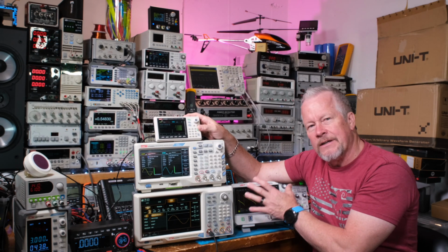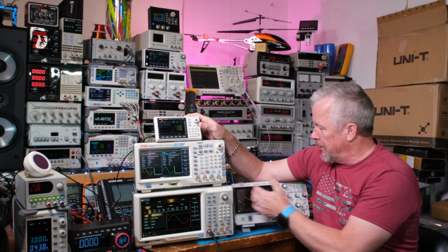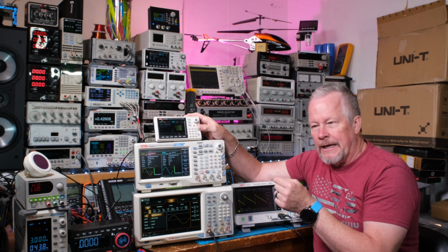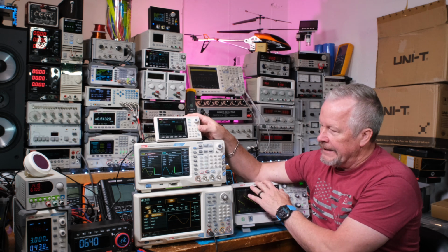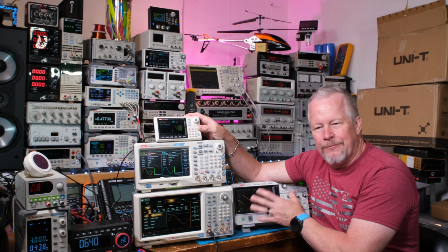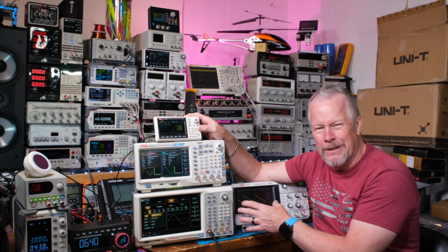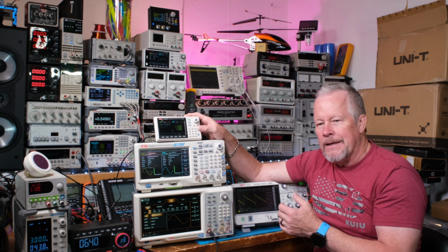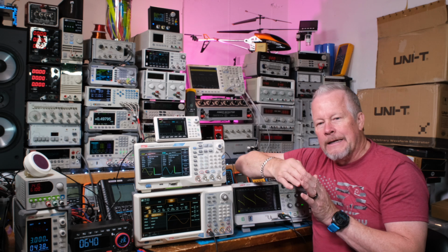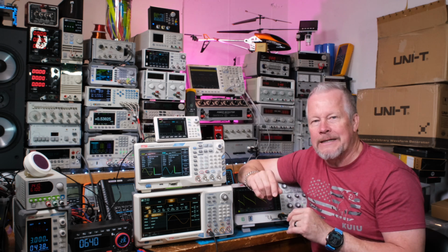All right, so like your oscilloscope, you have that vertical resolution we talked about, that so many staircases, right? But you also have that Nyquist theory, you have to have at least 2 points to recreate the frequency, right? So really, with scopes, they shoot for 2.5 times. Technically you need a little bit more than 2, even though Nyquist says 2. There's a caveat that you can't start at 0, because your 2 points could always be at the 0 line, so you couldn't recreate a signal. So 2.5 takes care of that issue.